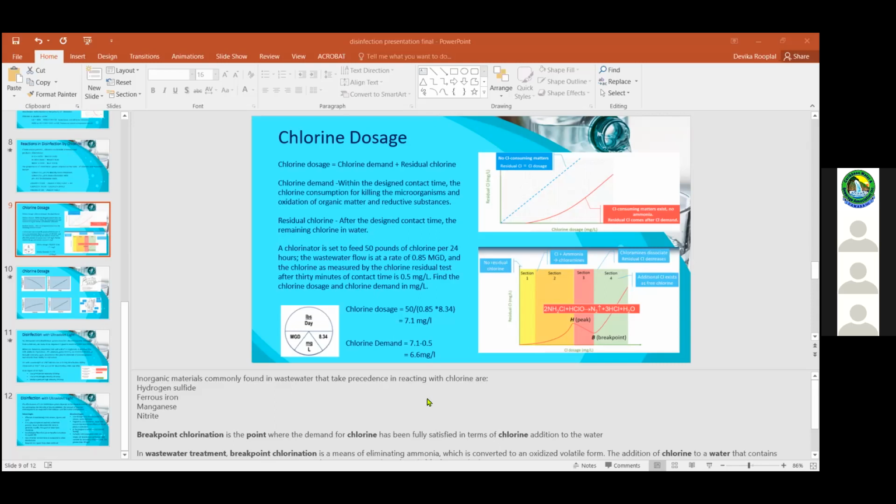So if you still have any little thing in your distribution system, remember you're maintaining a 0.3 or 0.5 milligram per liter concentration of chlorine. So you still have some chlorine in there that can continue to act as a disinfectant. But where you're using UV light, remember there's nothing remaining in the water. So it really depends on what your sampling point is, what your distribution is, because it's easy now to be recontaminated if your distribution network is contaminated itself.